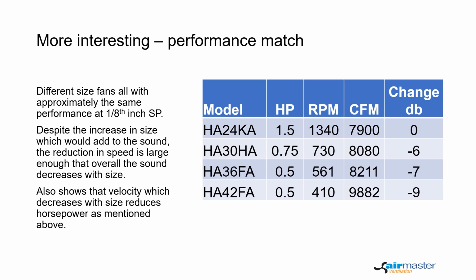Yes, absolutely. But what happens is that the reduction in sound due to speed in each example is actually greater than the increase due to size. Just the change from a 24-inch to a 30-inch is minus 6 decibels, which is a quarter of the sound power. Remember that 3 decibels is twice the sound, so negative 3 decibels is half the sound, or the inverse. So in this case, 6 decibels is half of a half, or 1/4 of the sound power.